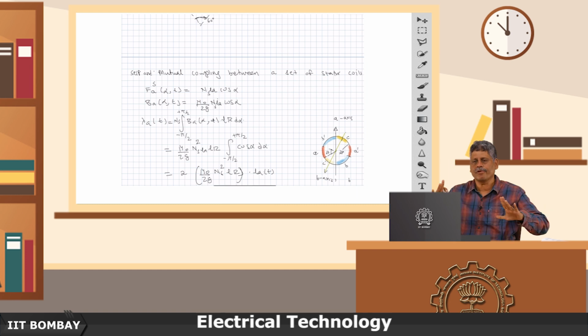So, there are 4 windings: A, B, C distributed on the stator carrying IA, IB, IC, and a fourth winding, which is the rotor DC winding carrying the current IR.